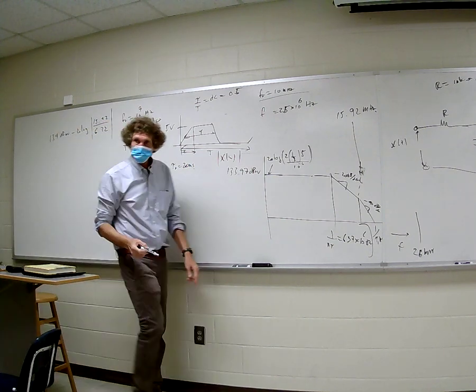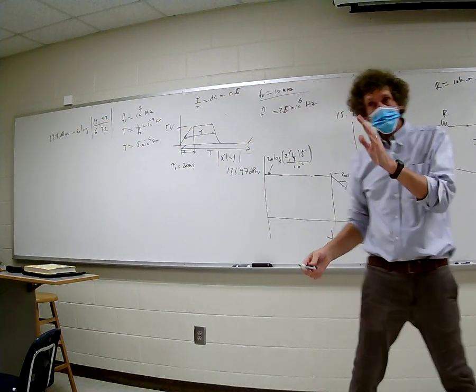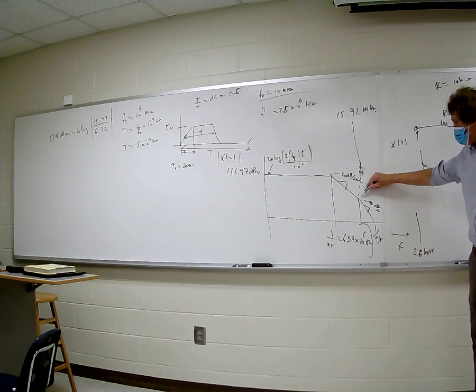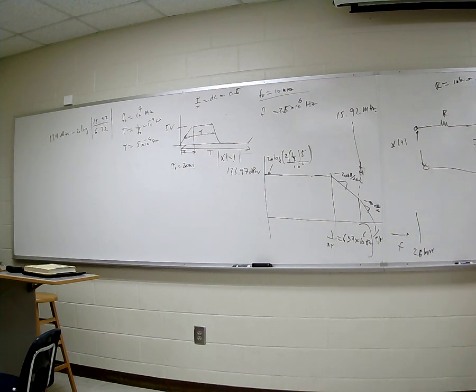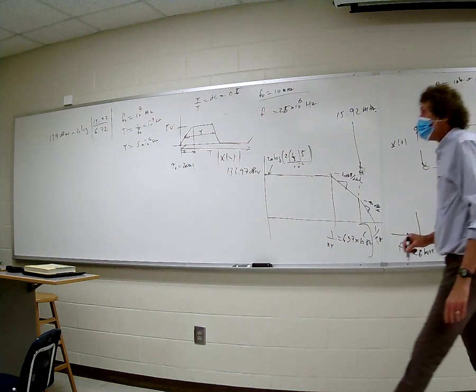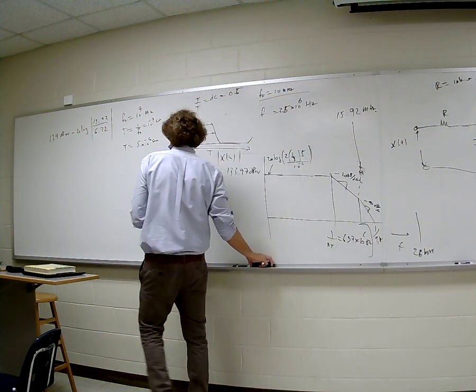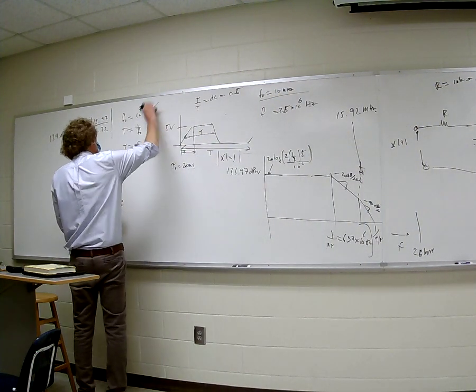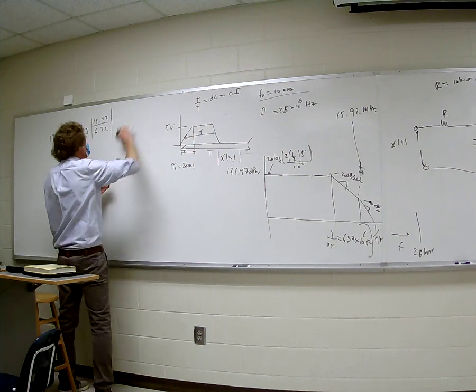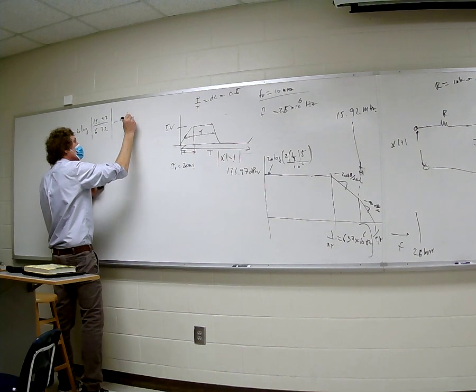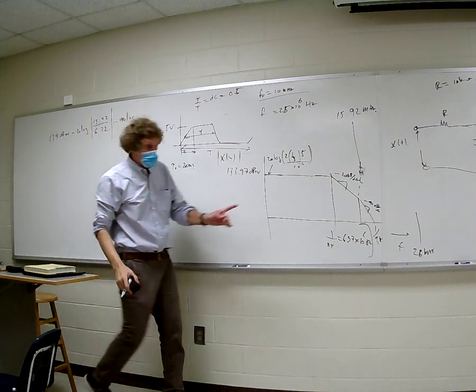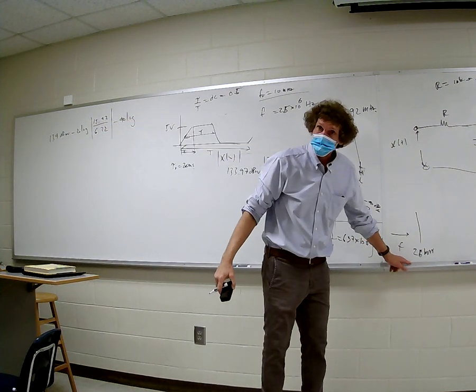Now I'm right here. Don't worry about the value. Now I'm at this point. You agree? Y'all see this, guys? I've got to go from here all the way up to 25 megahertz, right? But now it's coming down at 40 dB per decade. So now I'm going to subtract 40 times the log of the frequency I end up at, which is 25 megahertz.